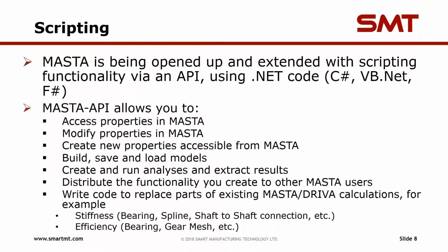You'll be able to send these scripts to other people. So yeah, you can either send them to other people in your team or make them available to other users on the internet if you like. And probably not in the first version, but in the longer term, we also intend to let the users replace bits of the MASTA functionality with their own code as well. For example, custom bearing or spline stiffness calculations or custom efficiency calculations. You'll be able to do these all using your own bits of script.